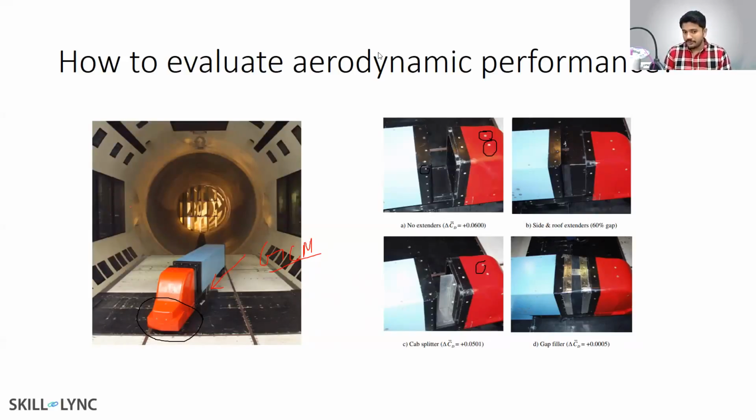So what people did at NASA is they made the model so simple that pretty much any CFD solver out there would create almost an identical mesh. So if the mesh is identical, all the results boil down to what governing equations you're solving, what is the algorithm that you're using to solve, what type of turbulence modeling schemes you use, right? So you can basically do a validation study, and that is the first thing that everyone needs to do.